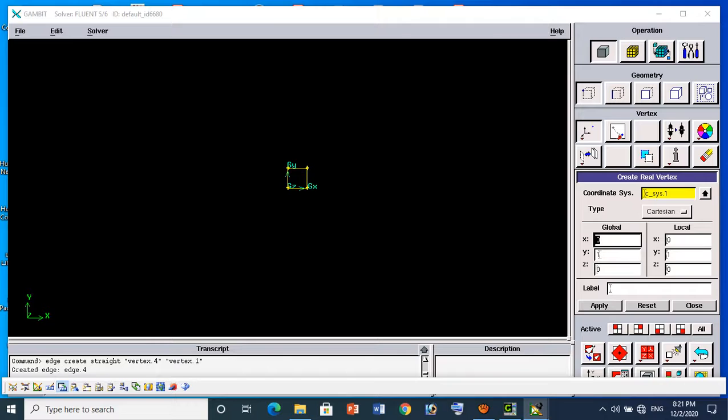I created one point, then in the x direction we will give -5, and in the y direction again -5. Here it will create a point. Similarly, this point is not good, so we will give -10 over here. Okay, fine. And -5, then +5. Similarly, in the x direction I will keep 20.